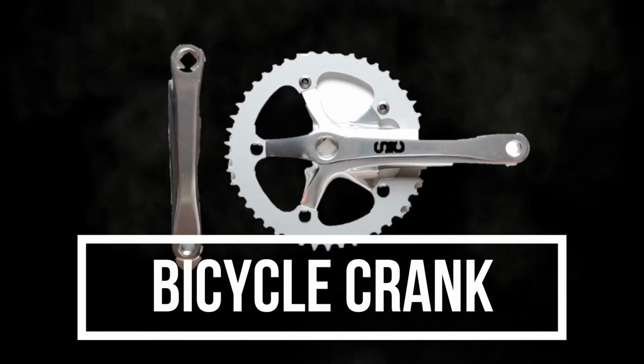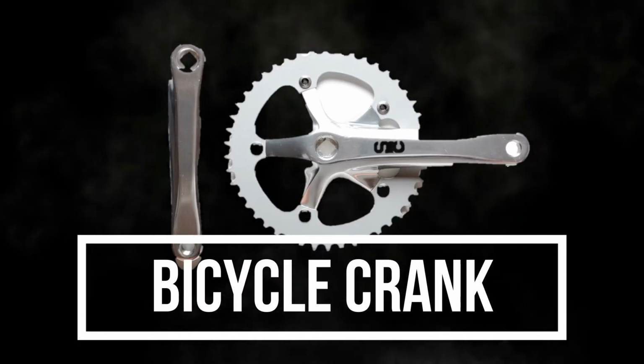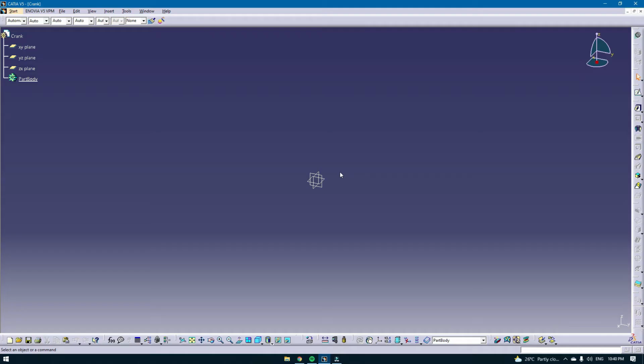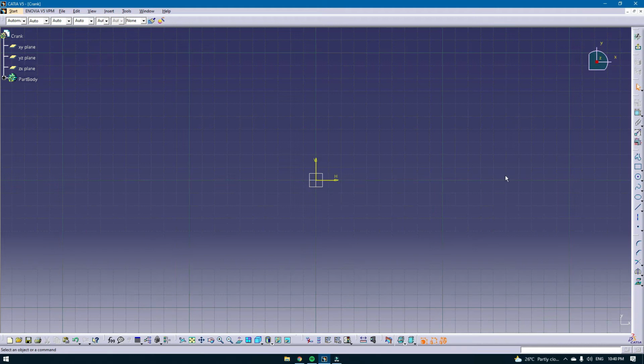The product we chose is a bicycle crank arm, and this is our CAD file in drafting mode. First things first, we need to choose the axis that we need to draw on by clicking on the sketch button and then clicking on the axis. For this part, I will be setting the XY plane. Then we need to make the circle, create it, and constrain it.